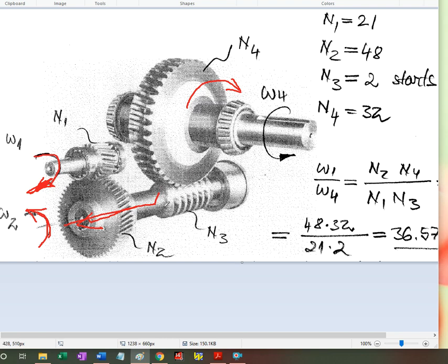I need to clarify, but again, having the pair at hand, you can inspect them and tell whether this is left hand or right hand. So this is a question, but otherwise the procedure would be like the one that I explained. Imagine you have a corkscrew, you hold the gear fixed, you turn the screw. Is it advancing away from you or towards you? You push it back in place, and what does the wheel do? At that instant, when you push it back in place, it acts as a rack and pinion.